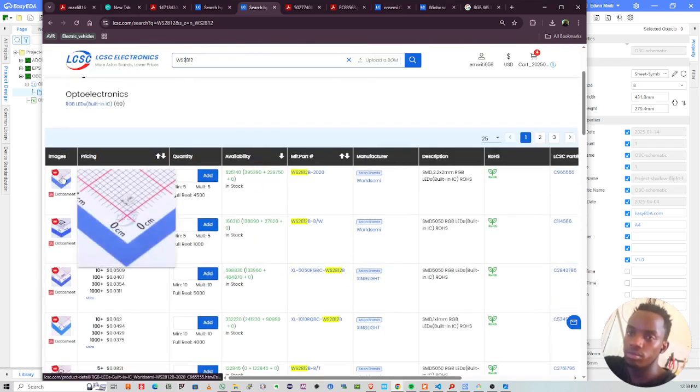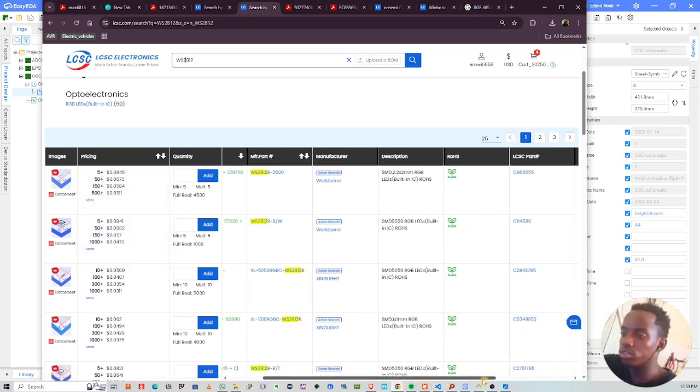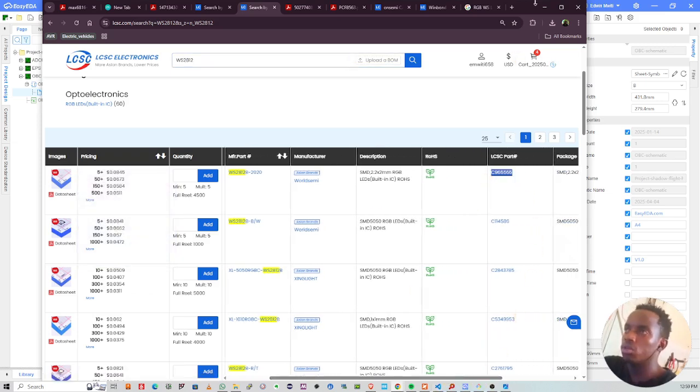These guys are good, and the reason I'm using them is because they are RGB, first of all, so I don't need three different LEDs for three different colors. Also, when I write the firmware, you'll see that when we need to show different states, we can show different colors. We can pulsate, we can blend colors, we can dim with PWM and stuff. So it's very easy and it makes the cost of the whole device low. So I'm using 3-in-1 LEDs.